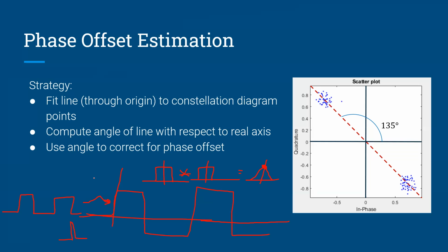Like how often would a microcontroller check if it's received useful information? In general, you have to be listening all the time, but it really depends on your particular system. What you could do is just have a running cross correlation where you're basically sliding this function along what you receive, and do it continuously. Yeah, okay, that's right. Though the actual implementation of that in an MCU can be a little tricky.